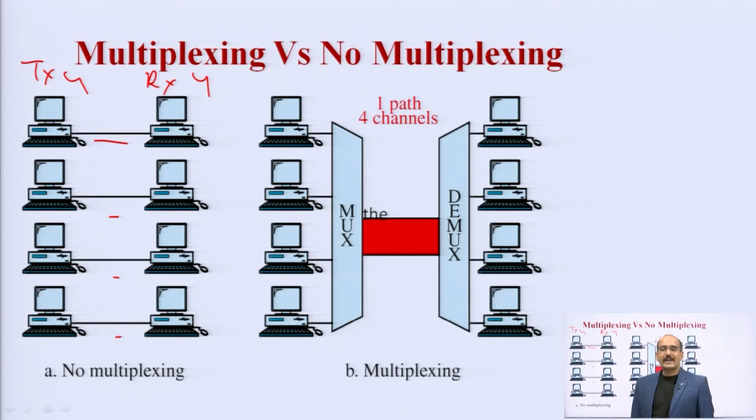So, to avoid that particular messy situation, multiplexing is going to be done. That multiplexer is basically a unit which is controlled by some kind of select signals. In this particular digital arrangement, this multiplexer is going to use this channel or path for all these 1, 2, 3, 4 users.